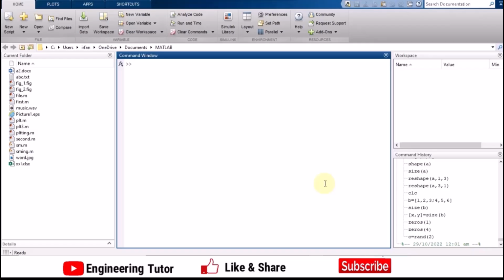So, another very important video which is related to the MATLAB, and today we are going to discuss the symbolic expressions. So what are the benefits of using the symbolic expressions? In the previous video we have seen that in order to solve different equations we have to write their coefficients. With the help of the symbolic expressions we may write the variables in their original form, and then we can process them as we want.